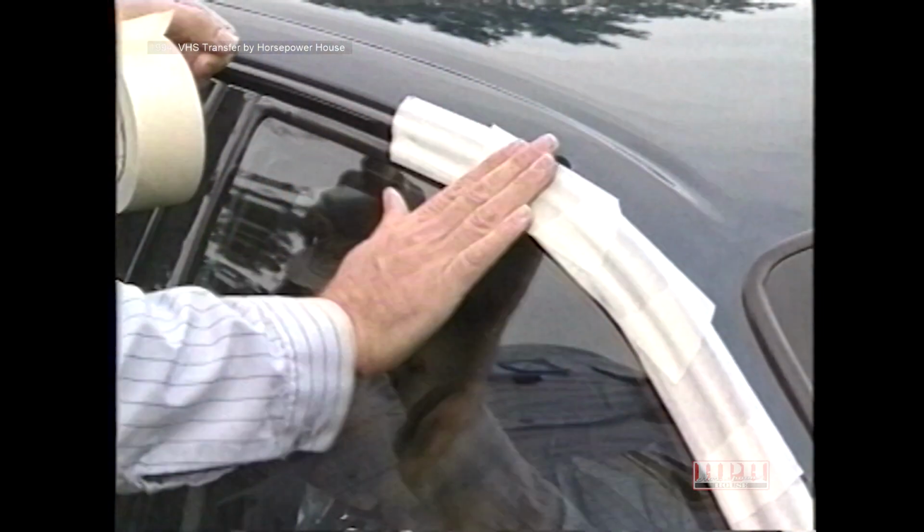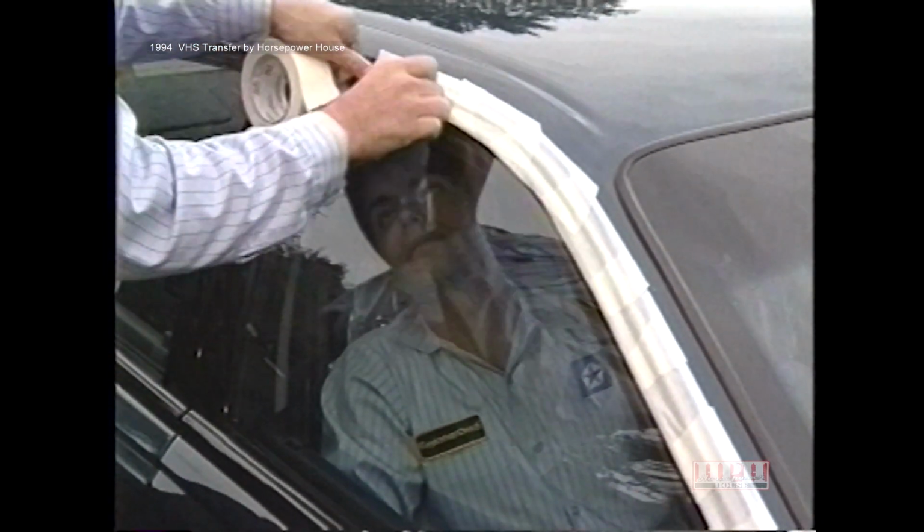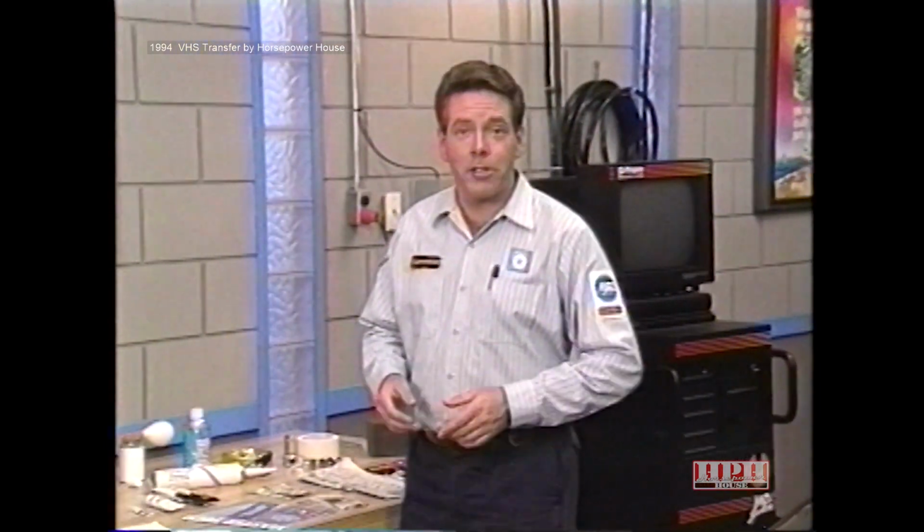If you're not certain of the particular problem, apply pieces of tape approximately 5 inches long to the area. Begin at the bottom and overlap the pieces as you go up. With the masking tape applied, resume your test drive. If the reported noise can still be heard, the leak is elsewhere on the vehicle. If the sound has changed, you may have narrowed the problem, or there may be an additional leak elsewhere on the vehicle.